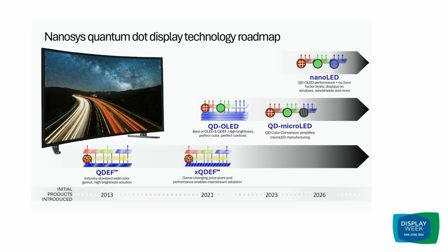If you move up, we consider these applications to be photoemissive, so they still rely on excitation from a higher energy photon and down conversion to lower energy colors. But the emission happens on the direct pixel level instead of broadly in an LCD, as in these lower photoluminescent applications. So some of these types of displays that you'll see coming out in terms of technology are color conversion from quantum dots on direct pixels again. These can either be blue OLED pixels or, slightly further in R&D, color conversion on micro-LEDs.